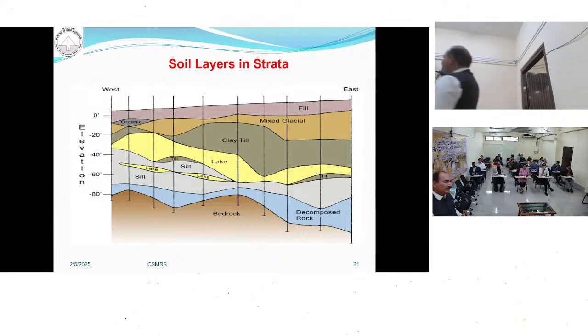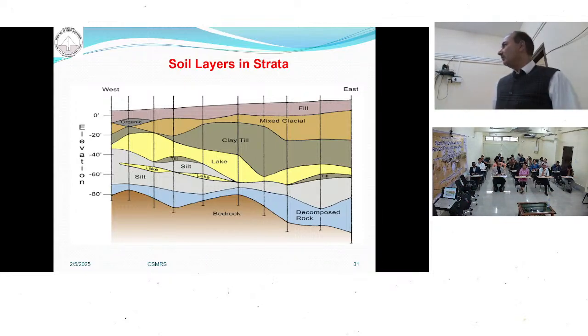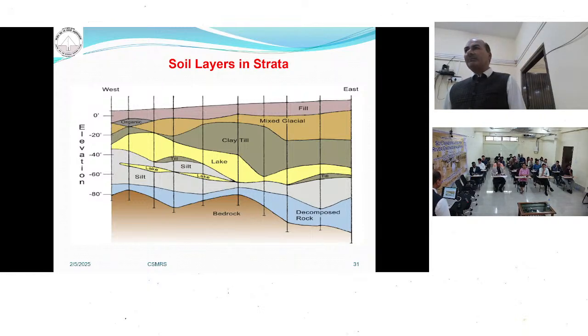You know, it is planned. These are your boreholes, your drill holes. Depending upon the investigation through the drill holes, we have made a picture, drawn the maps, which show what is the thickness of the different layers, and you collect the sample and test in the laboratory. You identify what are the properties of these layers.